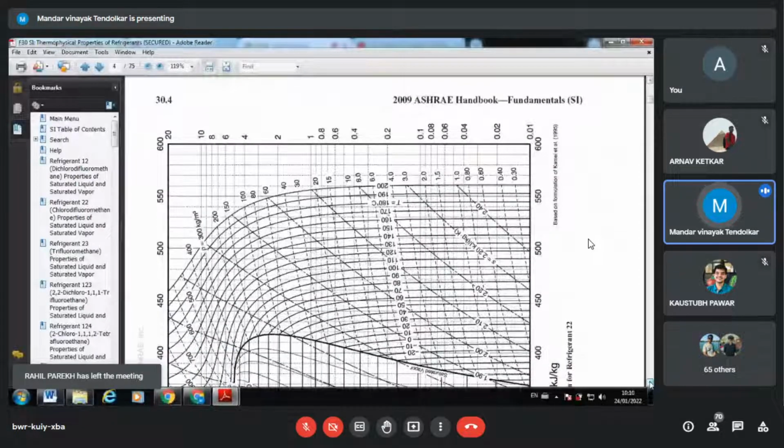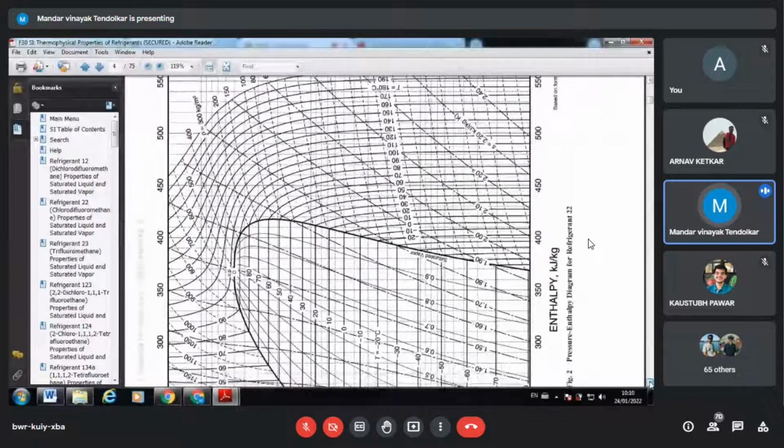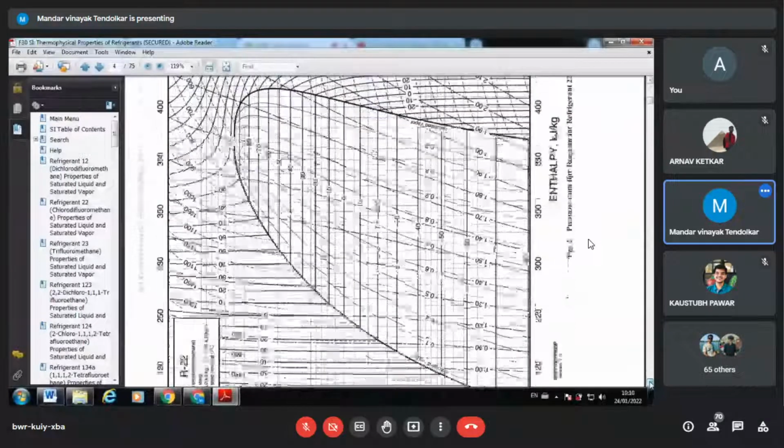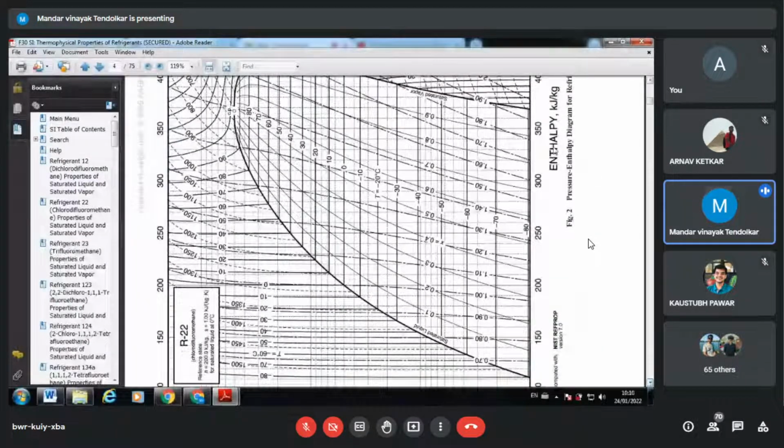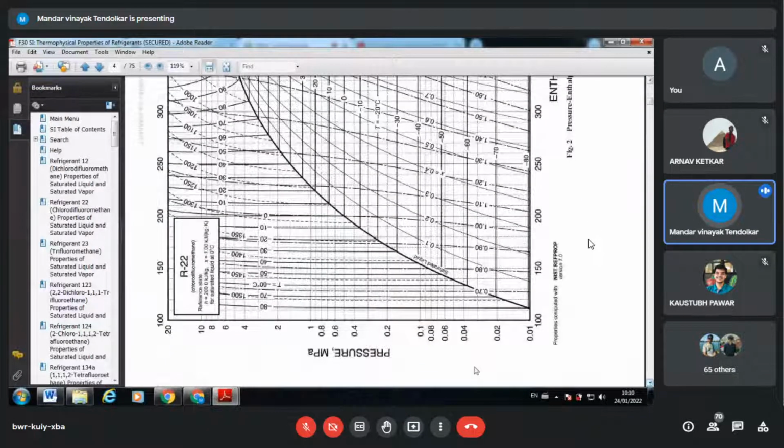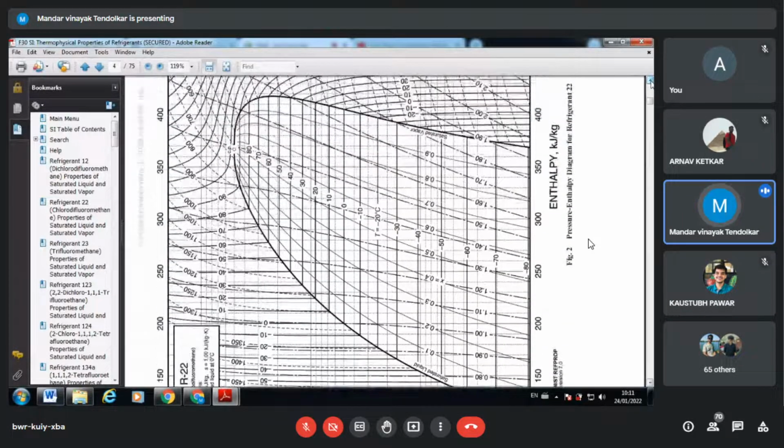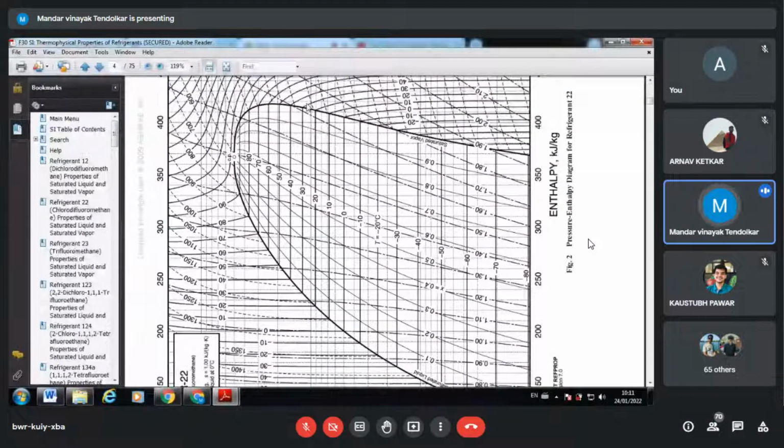And this chart is a slightly different version. I had not covered it in theory, but I am getting you some acquaintance with this. Here, the x-axis is enthalpy directly. Okay. And your y-axis is pressure. So this is called pH, pressure enthalpy chart. So the moment I locate the point over here on this pH chart, let's say somewhere over here, for example, then you directly take the x coordinate and that is your enthalpy. How to locate this, I will teach you afterwards. But just get the glimpse that this is a type of chart which will directly give you enthalpy.